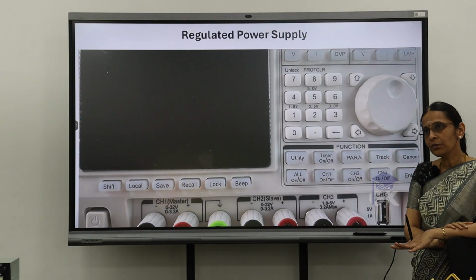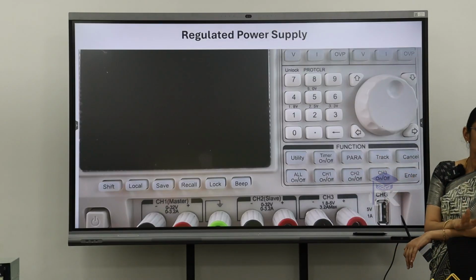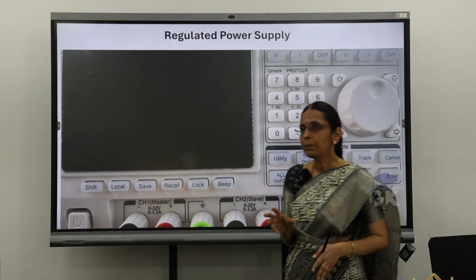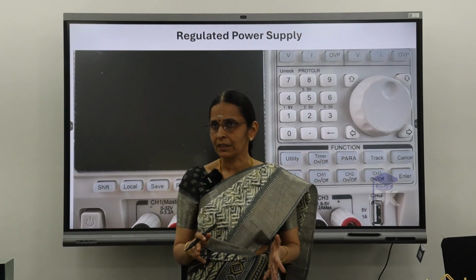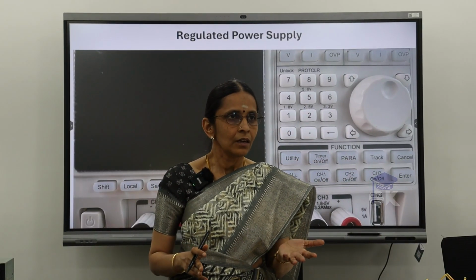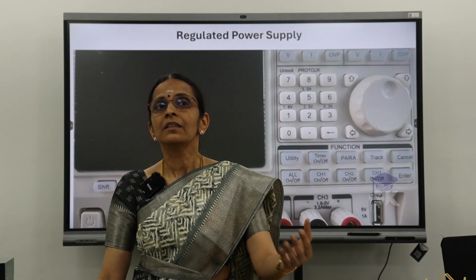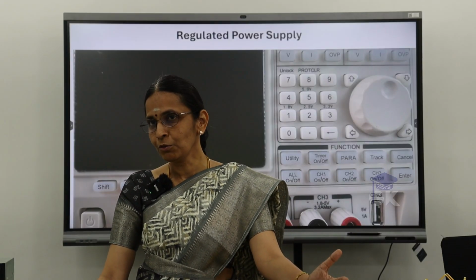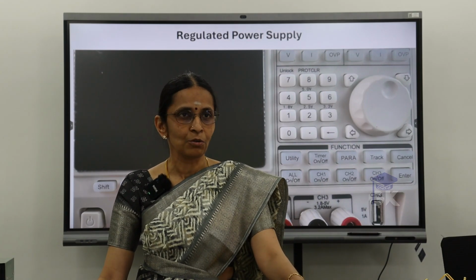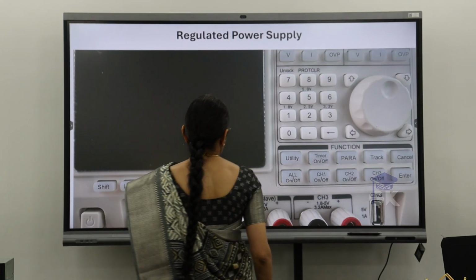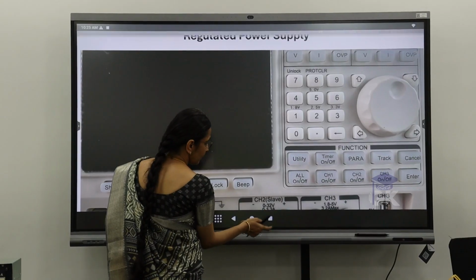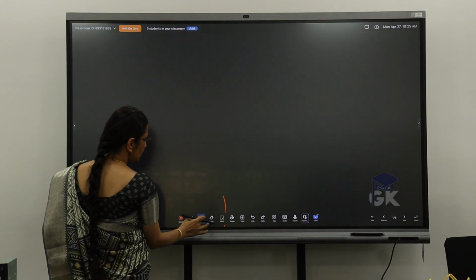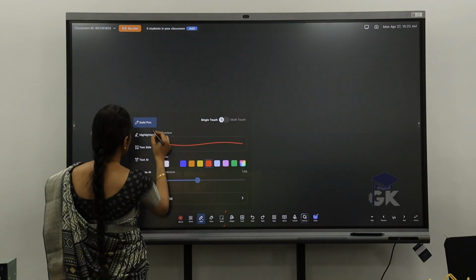So now what we are going to do is we will get used to both the types. Okay. And also I want you to rig up a circuit with your breadboard, a series circuit. You can take two resistors, provide a DC supply, measure the current, and measure the voltage across each resistor. I will only give you the circuit, you can do it, or you can take your own circuits. Better I will give the circuit so that it will be easy for you.